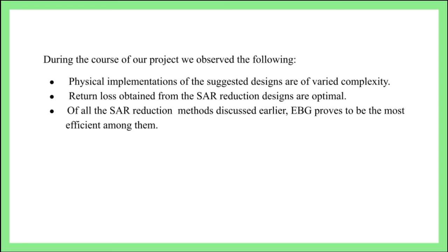In conclusion, the progress of the project can be summarized as follows. Firstly, physical implementation is always one of the most important considerations when it comes to designing antennas. Of the designs mentioned above, the EBG structure, due to its compact size and positioning, has a comparatively ideal design when interfacing with a PIFA antenna. On the other hand, the use of conducting walls and water walls, though effective, would tend to make the design bulkier.